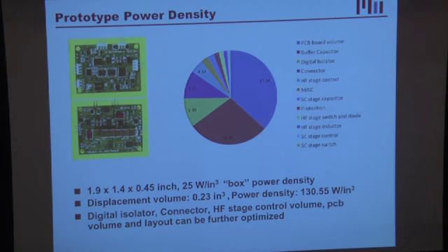All right? If I look at the actual breakdown of where my volume is in the system, the number one thing is actually just the circuit board. Well, that's clearly not true of conventional power electronic components. The number two thing here is the actual energy buffer, which I said doesn't really relate to the switching frequency. We've managed to make it somewhat smaller and get rid of the electrolytics by the way we're swinging energy from the circuit architecture. That's actually independent of us going to very high frequencies, but it shows you that if you use the right kind of circuit architecture, you can minimize those constraints.